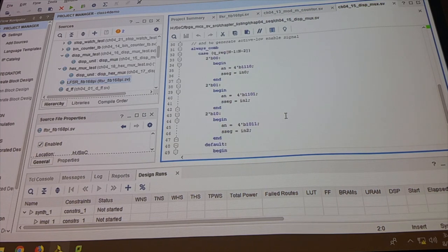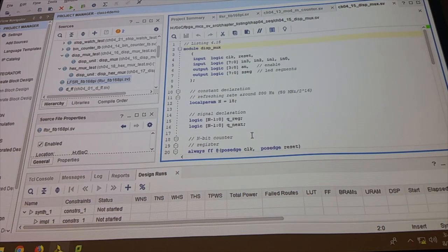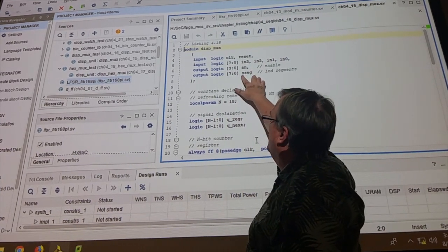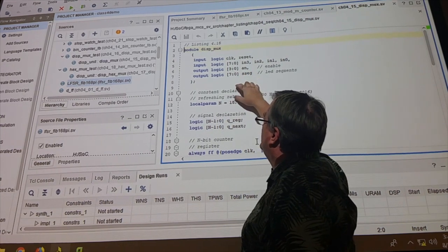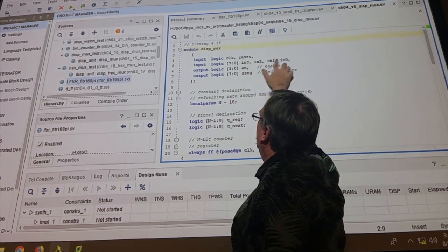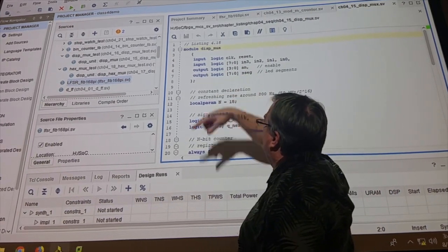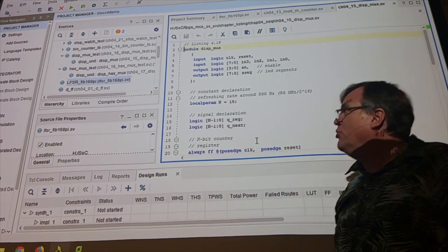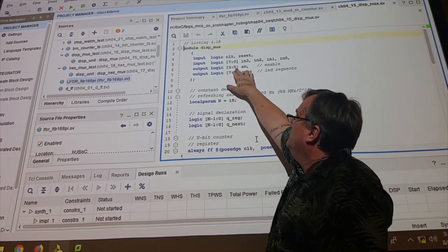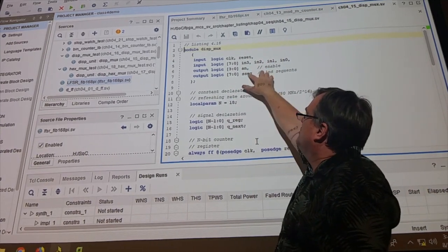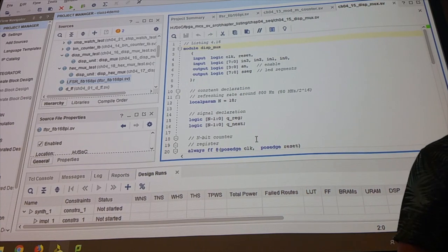And then you just have the different inputs. What's the display pattern for the 4 different bits? If you look up here, he's got the 7-segment display. That's the output. Anode is an output. You pass it the 4 patterns you want to display on the respective areas, and you send it clock and reset. And it'll pick which one of them should be displayed, i.e. the anode, give me power, and the appropriate one of these to be passed out to the 7 segments at the same time.